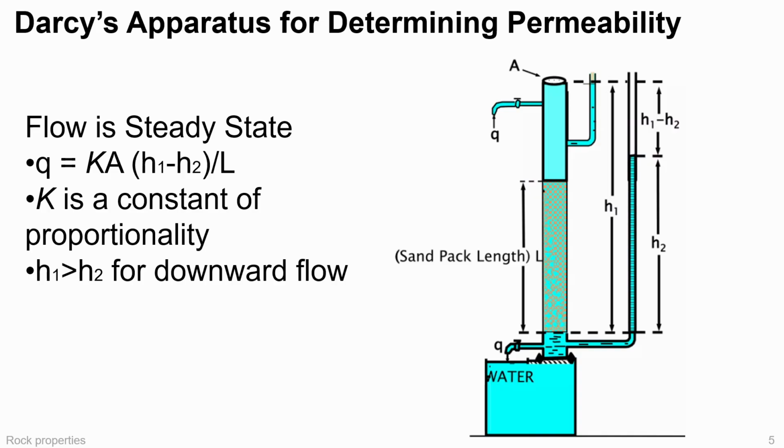This slide introduces Darcy's experiment. Steady-state flow through a porous medium is proportional to pressure head difference and area, and inversely proportional to length. Teach the meaning: if you increase pressure difference, flow increases; if you increase sample length, flow decreases; if you increase cross-sectional area, flow increases. Also teach assumptions: laminar flow, single phase, homogeneous sample. Darcy's law is the foundation of most reservoir flow modeling.